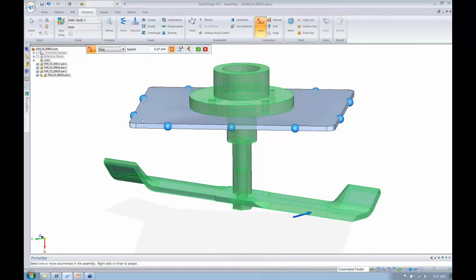The search distance here, I talked about the surface elements. They're represented by a 2D geometry that's usually placed at a mid-surface, in between the top and bottom surfaces of the plate. So those elements might not actually be in contact with this spindle, so I might have to increase the search distance to account for that. Or if I'm using no penetration, I could increase the search distance if there's a gap between my parts.